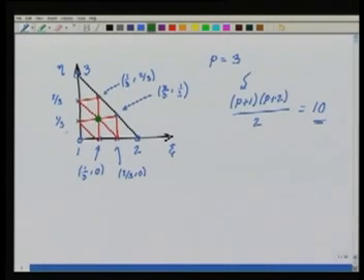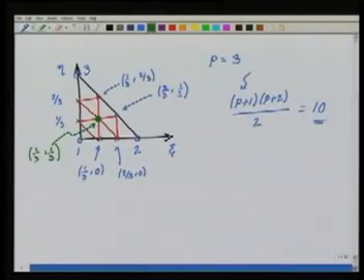This interior point will have a coordinate: it lies on the line eta equal to 1/3 and on the line psi equal to 1/3. So it will have the coordinate 1/3, 1/3. This is nothing but the centroid. So this point is another node for us. This becomes the 10th node. So our shape functions are now defined.